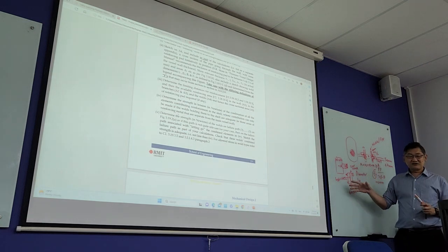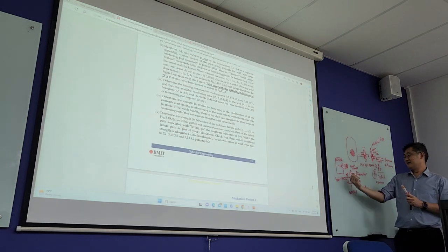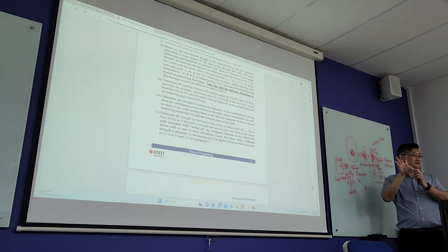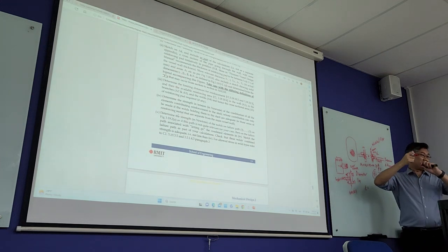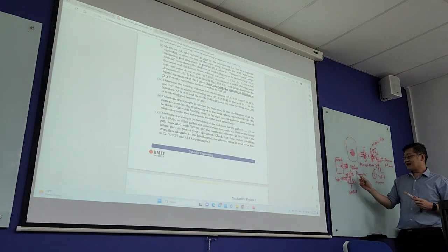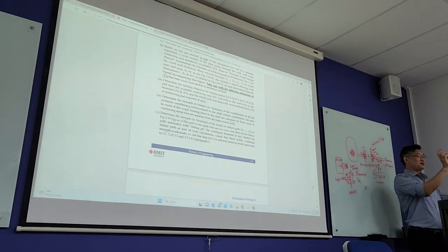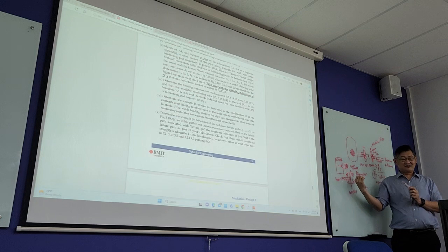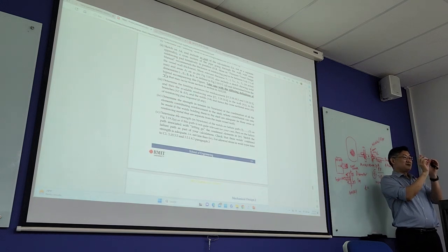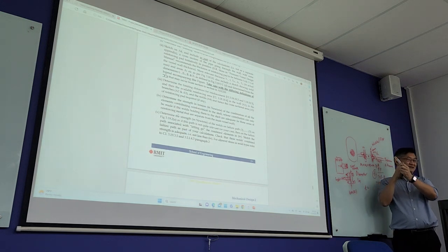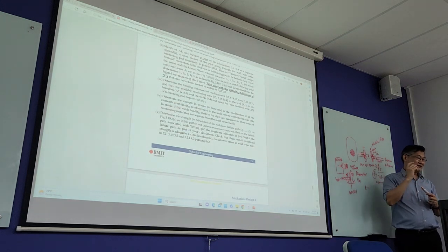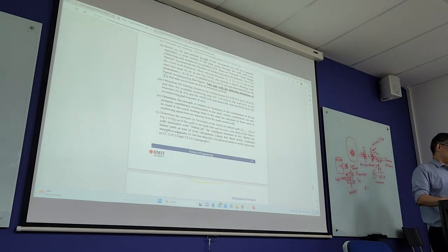But when there is pressure from the compressor, the force now comes from the other side against the bolt. So in this case, your gasket, instead of being compressed, because of the force coming from the internal vessel, will decompress a bit, because it goes against the bolt force.